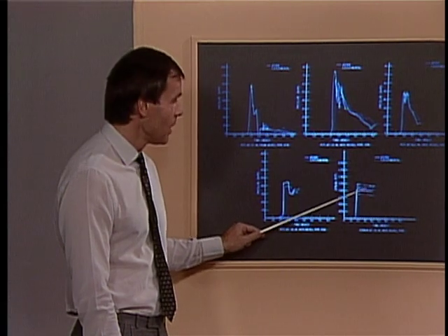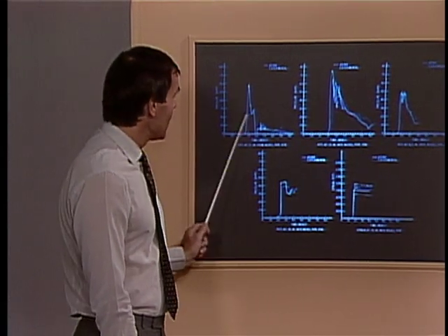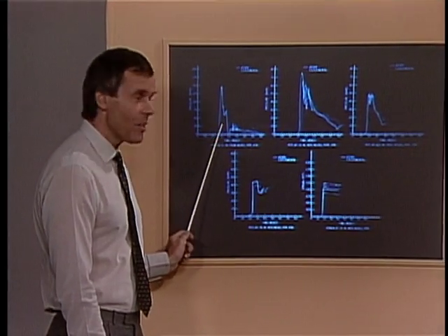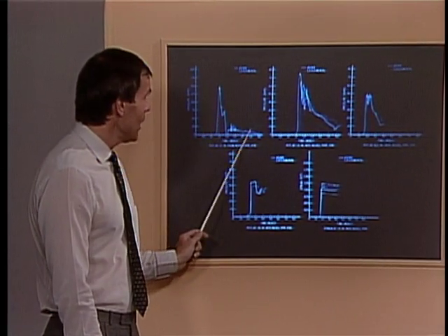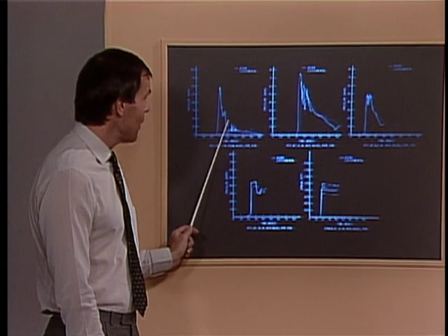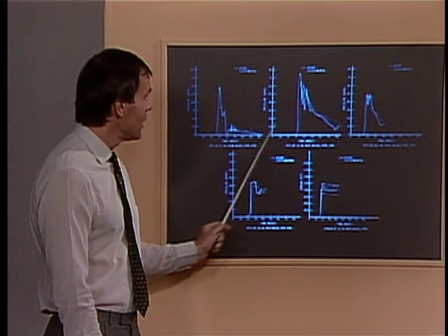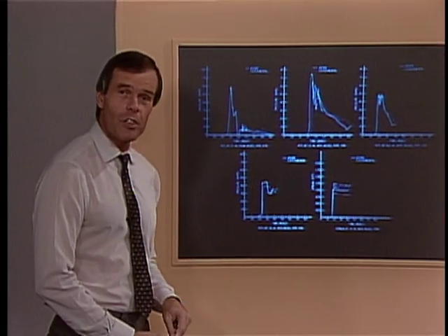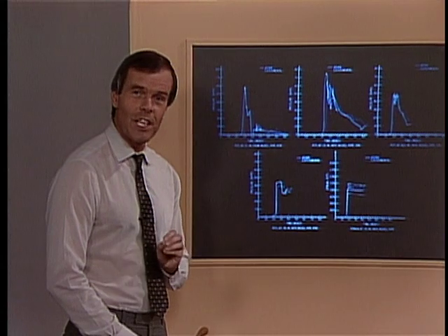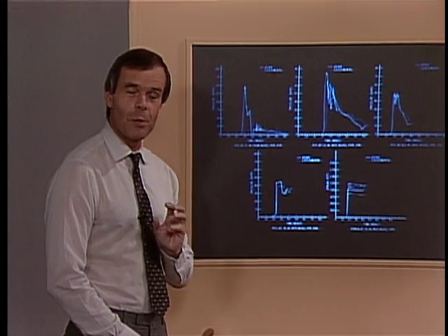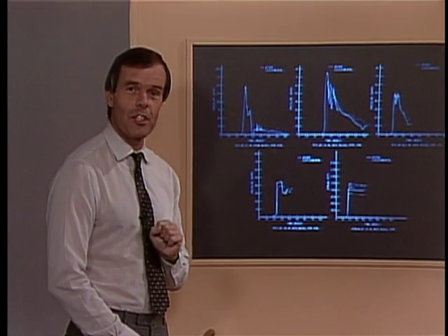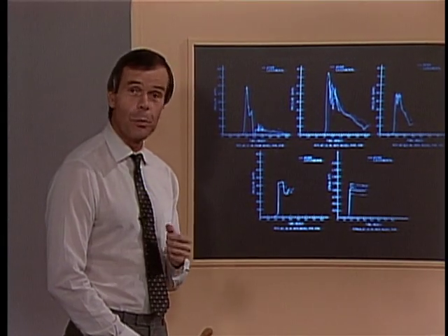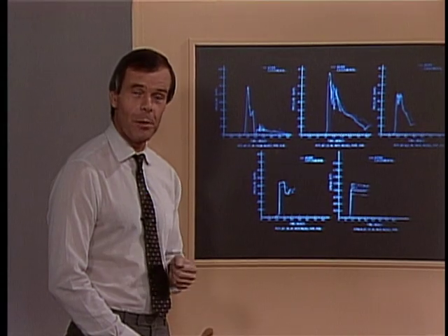I should also point out that the comparison of the ADINA results with the experimental results is really very good, except that we don't pick up these high frequency oscillations that have been observed in the experiment. Well, the ADINA finite element mesh that we used in this analysis is not able really to represent these high frequency oscillations, and of course that is certainly one of the reasons why we could not hope to pick these frequency oscillations up.